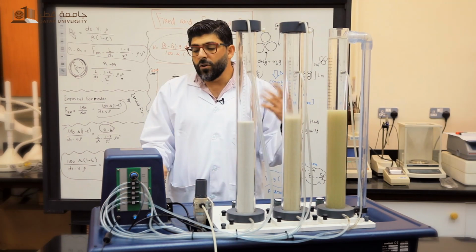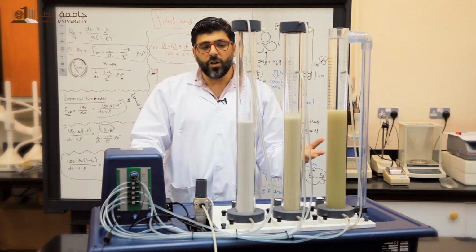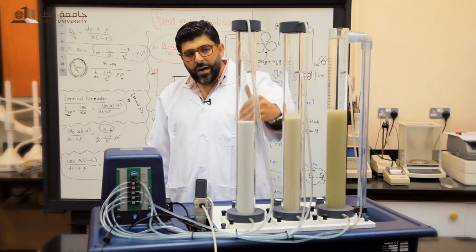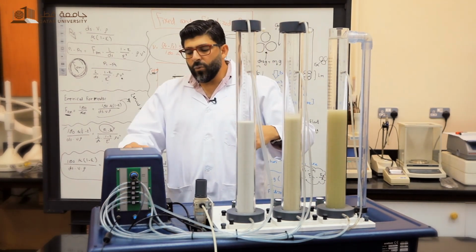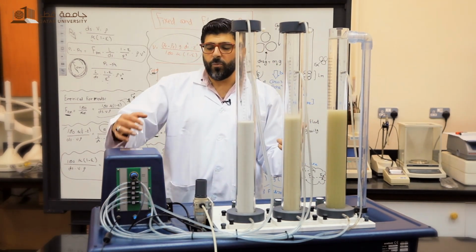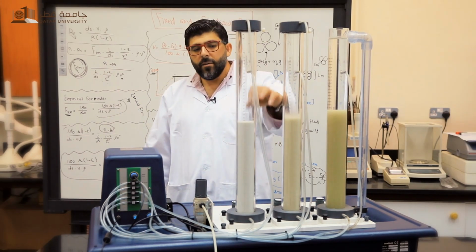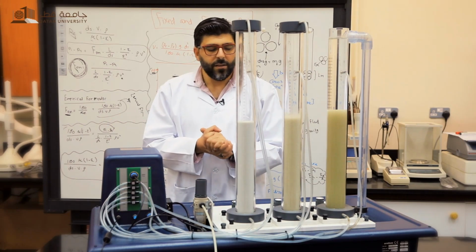You also notice that there is no more increase in pressure drop when the bed becomes fluidized, while the height increases. When it was still fixed, the pressure drop was increasing, while there was no increase in the bed height. So that's it. Thank you so much.